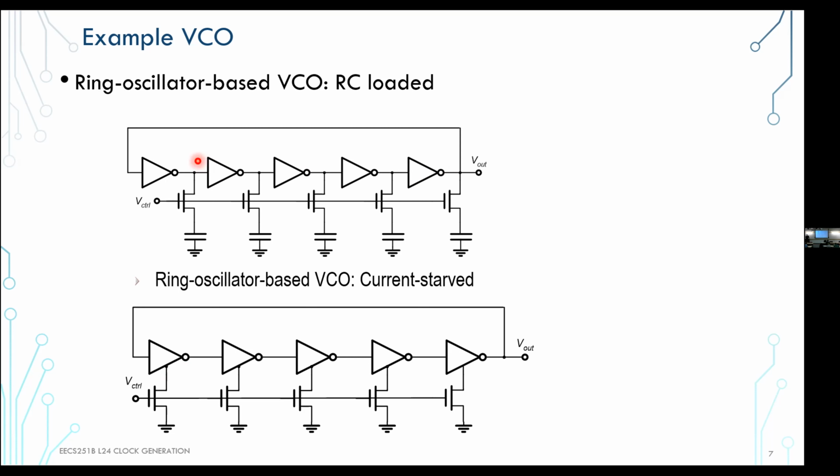This is typically used in, let's say, high-speed I/O, where your bit time is nowadays like 10 picoseconds or 20 picoseconds, and therefore you cannot afford a lot of timing error. You typically want 0.1 picosecond type root mean square errors on that clock. Here, if you have a few gigahertz clock, you can afford to have a few picoseconds of jitter in total at the output of your, let's say, clock generator. So these types of ring oscillators are reasonably good.